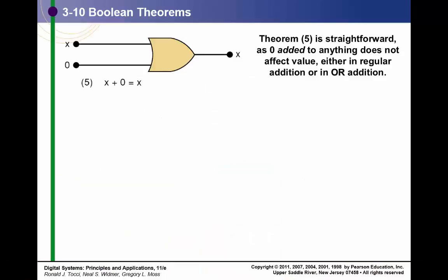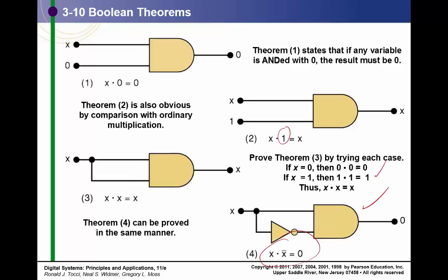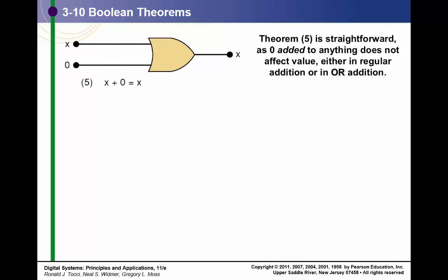Now that was just kind of a side note, that discussion regarding this being a pulse detector. For right now, do not worry about that. I'm just pointing out that even though we say the output's always going to be 0, this circuit is used from time to time. It's a very common way of detecting a pulse edge, and it has actually created problems in some cases.